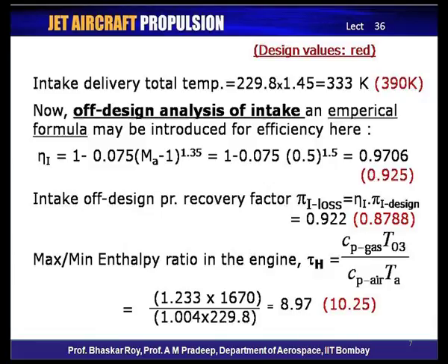Contrast this to the design point intake efficiency, which is indeed 0.925, and as a result, we can say that the intake efficiency at off design condition is actually higher than the design point intake efficiency. This should not be a big surprise, since it is now operating at Mach 1.5, which is a lower Mach number, and the shock losses would be far lower than at the design point, which was at Mach 2. So, this higher intake efficiency should be quite acceptable.